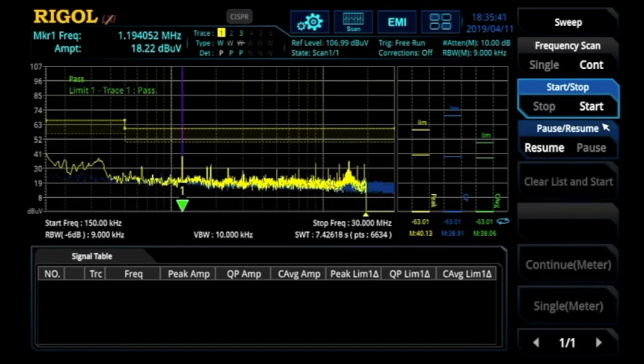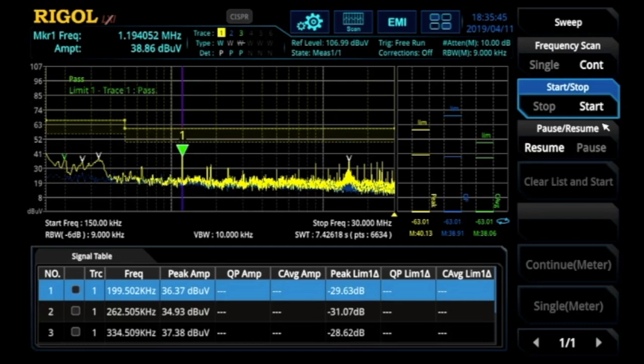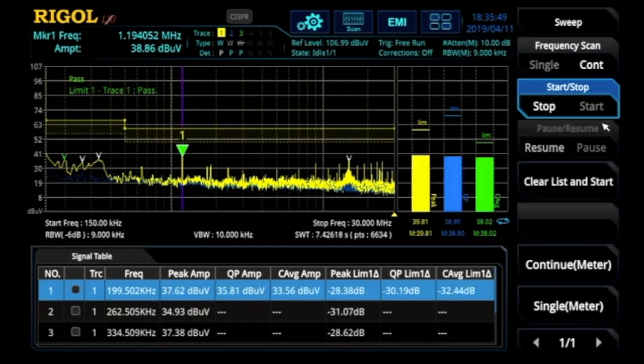So with the device on, we see a number of peaks across the conducted band. Right? We can identify peaks, and what's great about this is even though we did a peak test using a peak detector, now on the right we can see both the peak, the quasi-peak, and the CISPR average detector, and how they look at that peak frequency that's of interest to us.